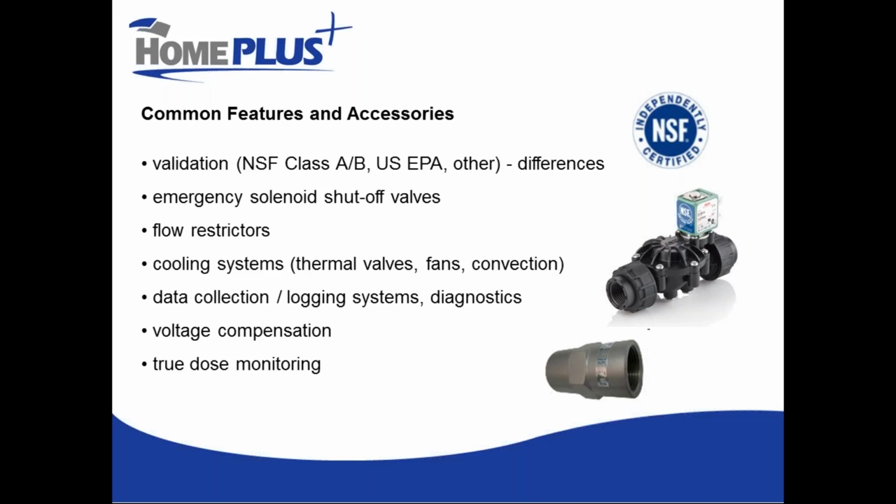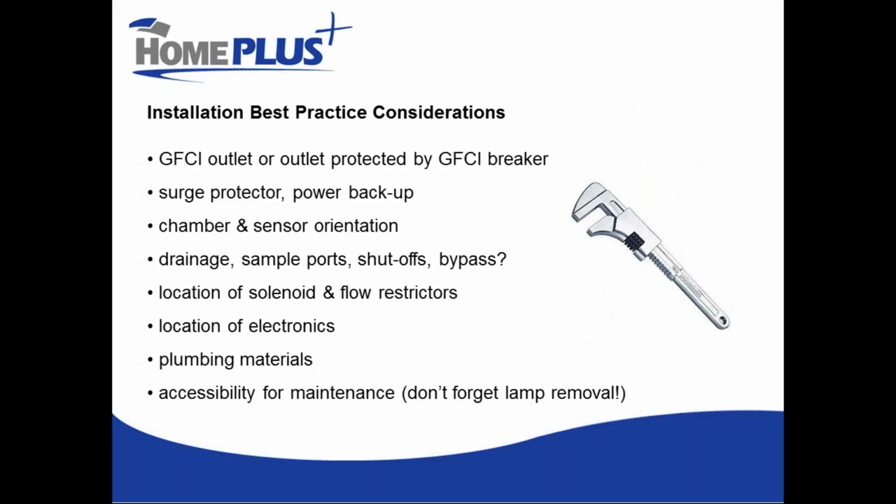And there's a couple of models now on the market that are doing what we refer to as true dose monitoring. Most of the monitoring historically has just been related to monitoring UV intensity, with the assumption in calculating the dosage level that they're always running at full capacity. And we all know that we don't always run our systems at full capacity. So by adding flow meters to the UV sterilizers, we can actually calculate the true dose based on the current intensity and our actual flow rate. And that can be very, very handy as a technology for us.